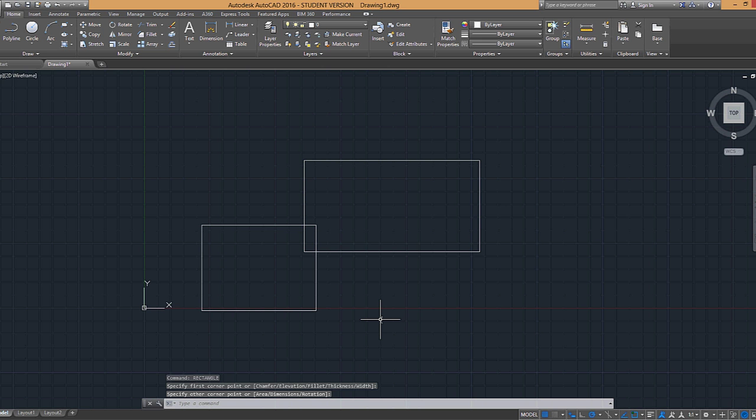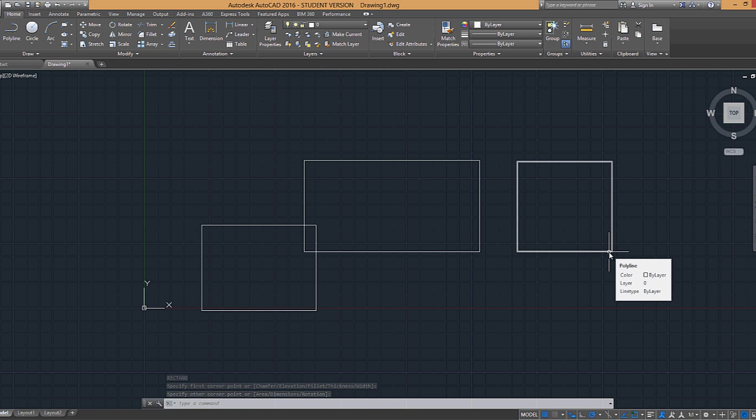Or I can use an alias. The alias is a short form that you'll have to memorize with each tool. If I type in REC, I can do the same thing. A lot of the tools will have a shortened version, which is basically defined as its alias.